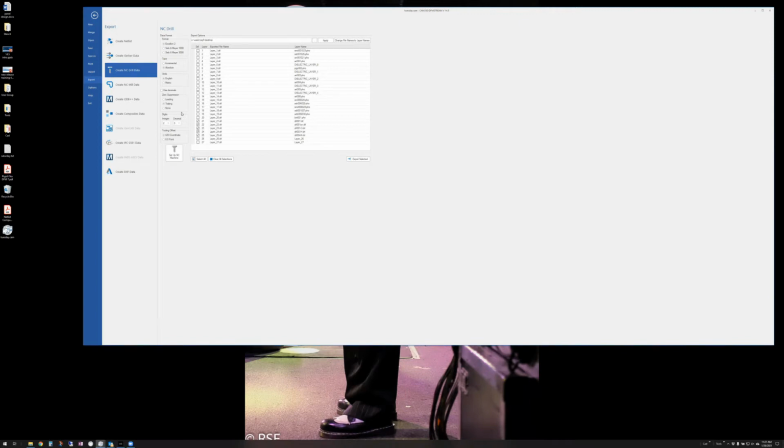So if you were thinking about writing out a CAD format from Gerber and NC, there's a lot of work that goes into that. Basically, you've got to clean up your data, make sure all traces end in the center of pads, and then build components. And then once you've done that, several checks you do along the way, and then you would export, if you had those capabilities, these CAD formats. But again, the advantage of ODB and 2581 is I don't need to have component information. But the disadvantage is I don't have component information. So if I'm trying to take it back into a CAD system, it probably won't come in.